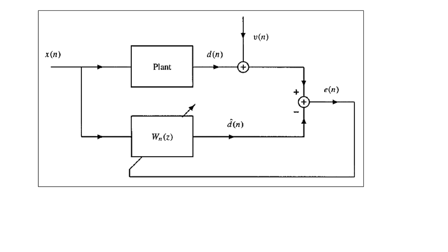Therefore the error sequence cannot be generated directly. Therefore, for the estimation of d of n, let us have another block schematic that will generate the sequence that may be used by the adaptive filter. These are the different points we have already covered, and here is the block schematic.